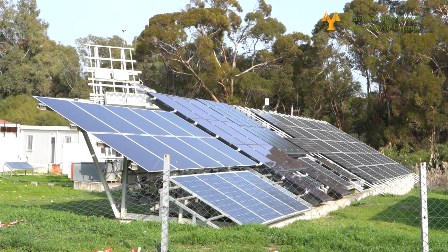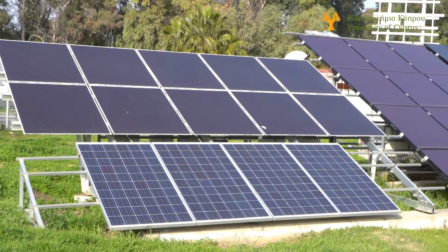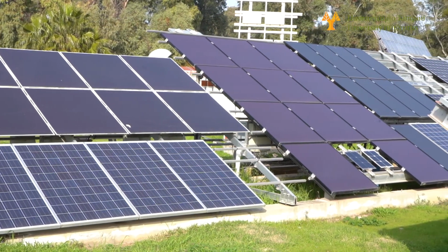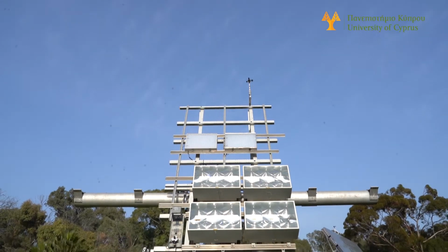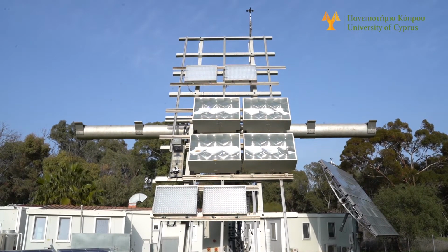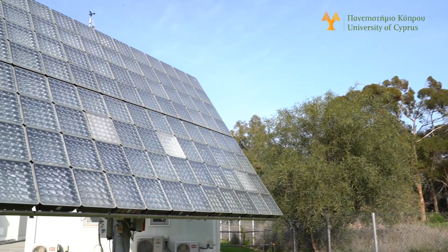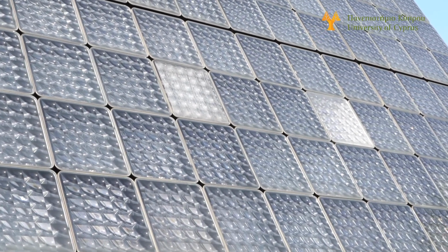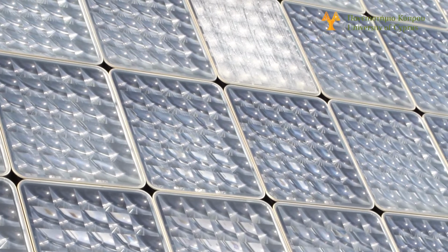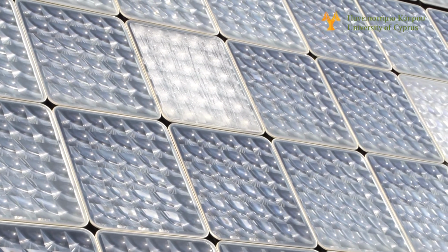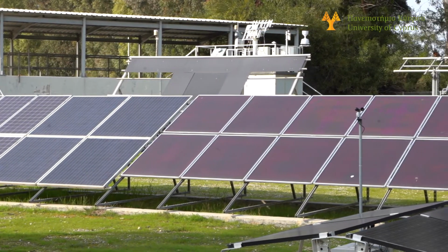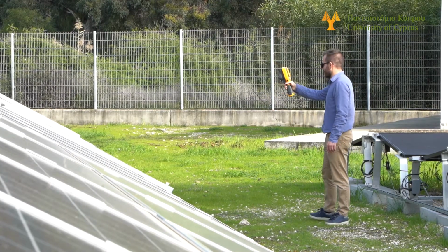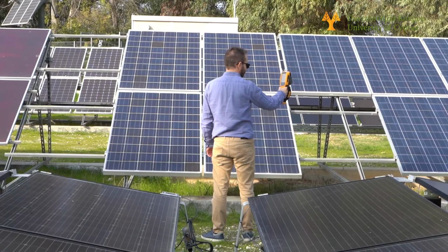The outdoor facilities consist of many setups that are used for research purposes and for service to the industry too. There are setups that evaluate new technology of photovoltaic systems. There are also long-term setups that evaluate the performance of different technologies of photovoltaics under real conditions. There are also other setups that perform NOCT tests for the calculation of temperature coefficients of photovoltaic modules.